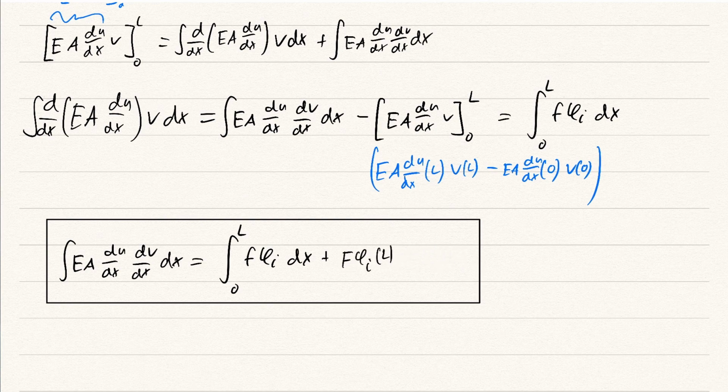Now we have this differentiation here. I can put this as well. Yeah, so we have the approximation and the basis functions over there. Let me just fix this. I'm gonna put these guys in there as well now. So I replaced this with the Galerkin method. Okay, so this is the complete Galerkin method for this elasticity problem now.